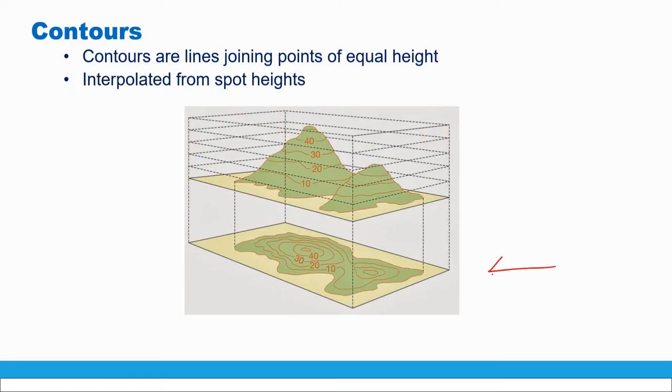After you learned how to draw contour lines, now you have contour lines like these, for example. And then the aim of today's session is to let you know how to construct and draw a topographic profile. The topographic profile illustrates the topography that's intersected by a vertical plane.